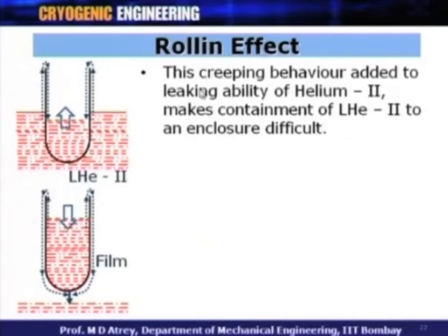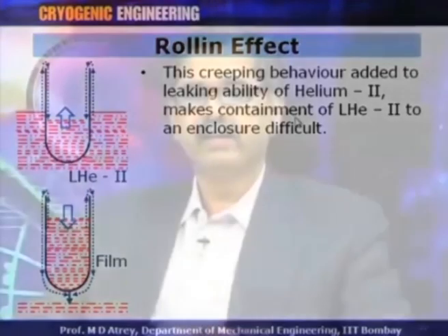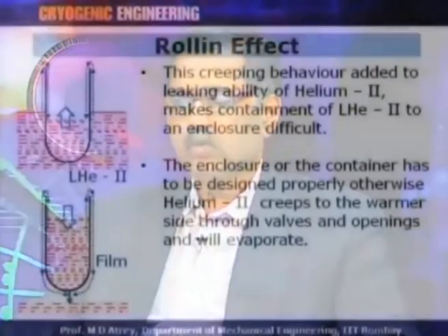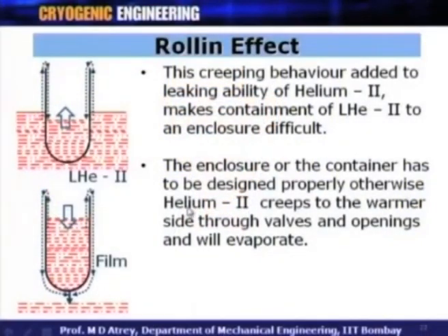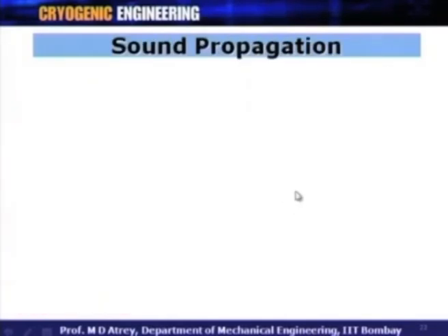These are very important aspects. If you want to store liquid helium-2, one has to be very, very careful. You should not have valves, you should have proper containers, you should not have cracks and things like that. The enclosure or the container has to be designed properly, otherwise liquid helium-2 creeps to the warmer side through walls and openings and will evaporate.